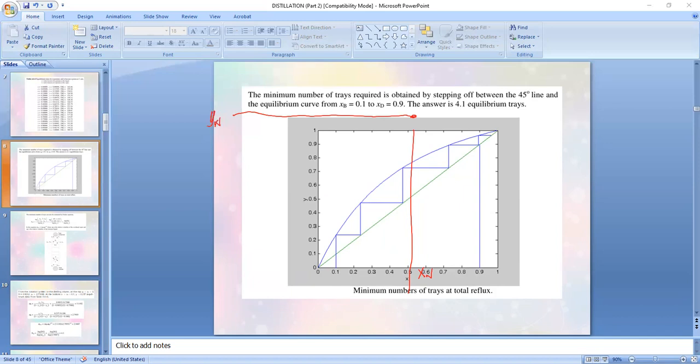Even better because you actually base it on the curve. The curve in the first place gives you the relationship between x and y. The curve is from this x and y. So this is it. In the bottoms, it's liquid, right? So this is your x sub 1 based on Fenske's equation. You go up until you reach the curve. Read here your y sub 1. That's it. This is the pair of values you will substitute for your alphas in your Fenske's equation.